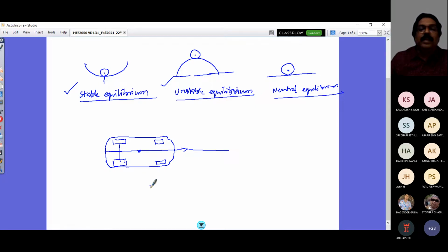If this vehicle is acted upon by a side force, such as a wind gust, with its resultant acting on it, what would happen to this vehicle is what is to be looked at. If this vehicle is originally an understeer vehicle, you know that it will go away from this disturbance.